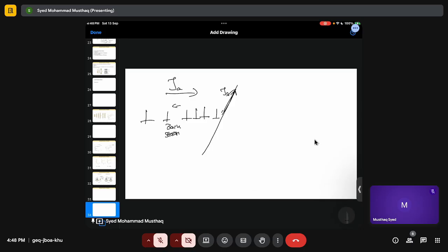Resolved shear stress. Let's say the number of dislocations is n, and tau c will be the critical stress required to initiate dislocations, or move the dislocations from one grain to another grain, or initiate the dislocation motion on this grain.